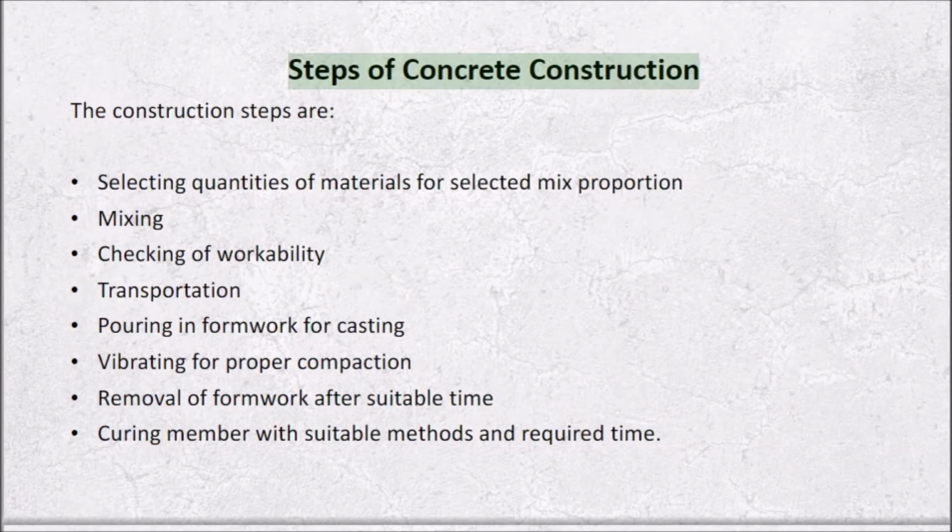Steps of concrete construction. The construction steps are: selecting quantities of materials for selected mix proportion. Mixing. Checking of workability. Transportation. Pouring in formwork for casting. Vibrating for proper compaction. Removal of formwork after suitable time. Curing member with suitable methods and required time.